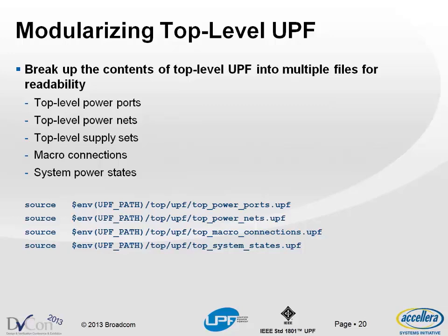So what we could do is use a source command. Source is different from load UPF in the sense that load UPF is for reading UPF files for a specific scope, and it applies all the UPF semantics while loading it. Source is just like a Tcl command. You can just source a file. What it means is it's just going to take the contents of this file and concatenate it while building the file. So source is just an easy way for us to break a big file into smaller chunks. It really does not make the file hierarchical in any sense.